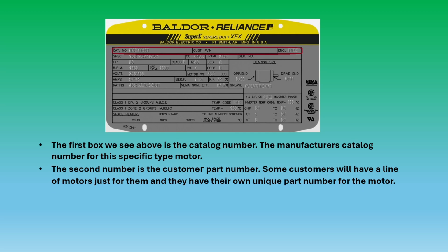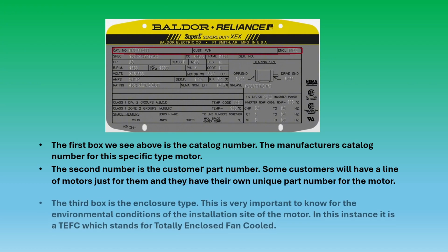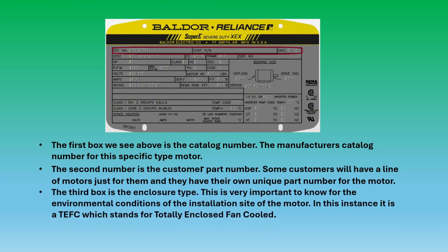Second number is the customer part number. Some customers will have a line of motors just for them, and they will have their own unique part number for the motor. Some manufacturers may be manufacturing 14,000 components a year of some type of equipment, and they always use the same motor. Well, they can have their own part number, which is useful for supply and ordering motors. The third box is the enclosure type.